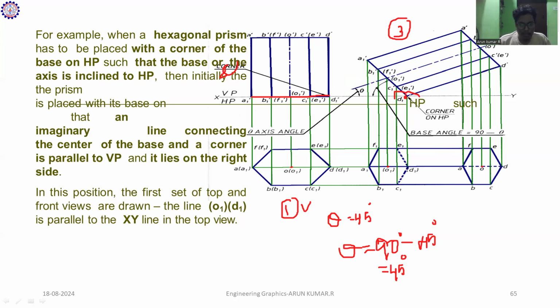From the 34, you mark an angle and draw the line. I already told you that the solid can be tilted, rotating in this direction, so that this point is fixed and this point is free. That is what I have to mention here. Like A1 dash, mark it here. You measure the distance of these two and mark them as B1 dash and F1 dash. Similarly, mark C1 dash and E1 dash here, and mark D1 dash. So this is the method to carry out the problem.